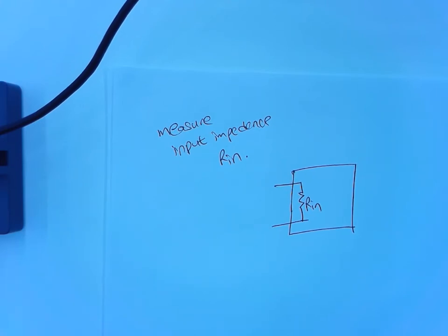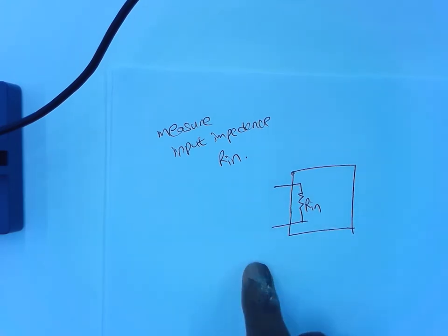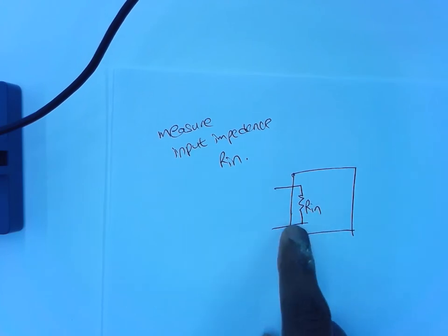So if I want you to construct a small circuit and figure that out, how would you do it? Like a hard Thevenin? What do you mean, hard Thevenin? Do you mean actually calculate it by hand? Right. Let's say I give you a box, and I say that's my amplifier. Don't use a digital multimeter to measure the input impedance. You have other resistors and everything in your lab. Make a small circuit, and I'm asking you to figure out the input resistance. How would you do it?